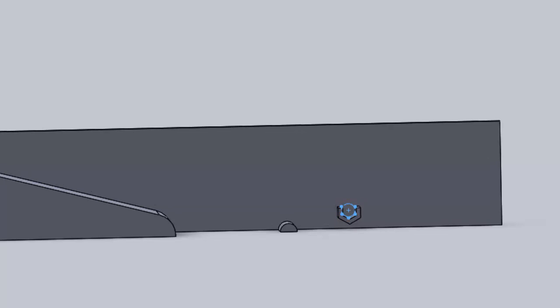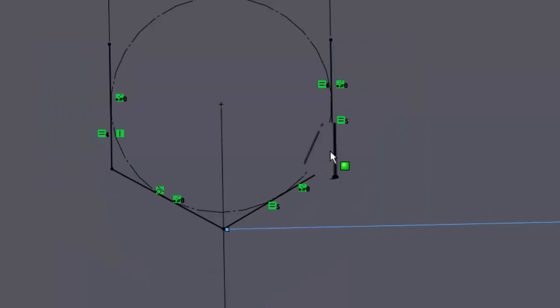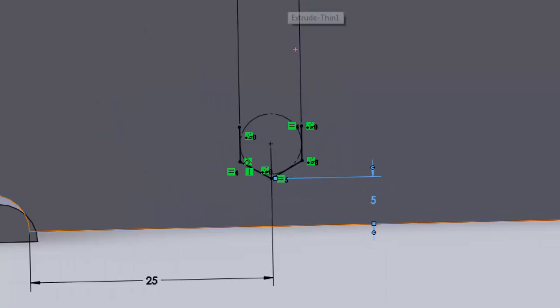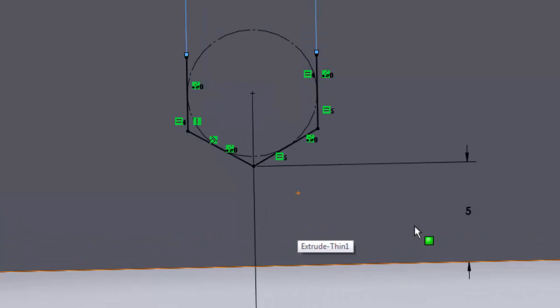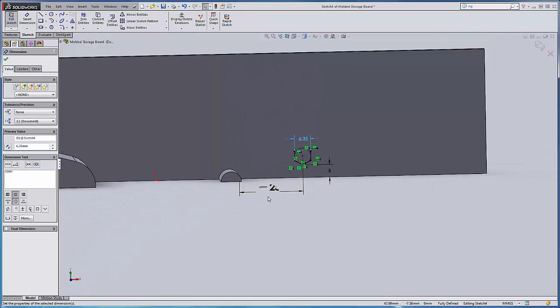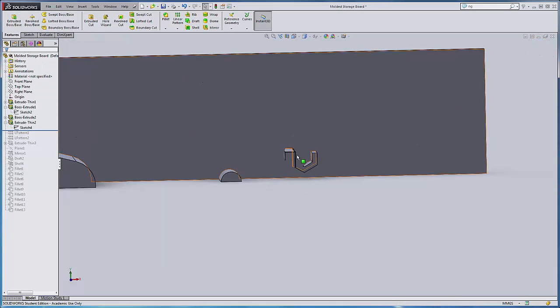And if you'll notice, this is a hexagonal shape. And all I did was I cut off the top two parts, made all the rest of these equal, gave it a dimension that was going to work right with ours. And so when you put your insert or your bit in there, it'll squeeze right in. And then offset it from the edge here a little bit and moved it down from where the crescent wrench is going to hang. Then I made that thin feature, and so it just expanded outside of that.